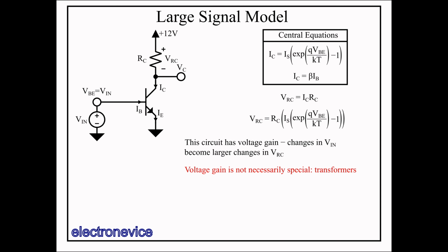To answer this question, we have to think about the power in and the power out. First, we think about power in. We know from before that at least with something like the 2N3904 transistor, the value of beta is around 30 minimum and often exceeding 100. So the base current is small with respect to the collector current. The input signal's power is equal to the change in Vin times the change in IB. We say change in because that's the portion of the voltage and current that the information of the signal is contained in. We also note that the output voltage is proportional to the output resistance.